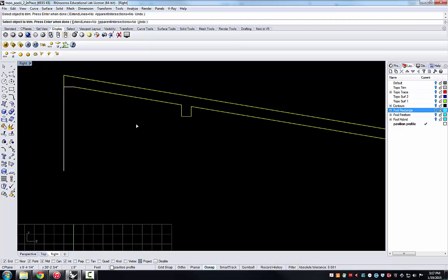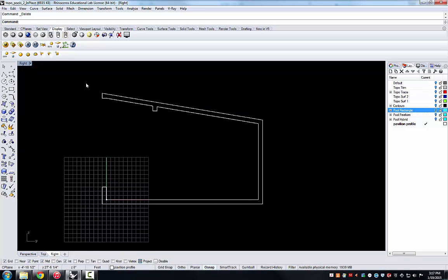To change the exterior profile of this, I'll delete the input line and step back. And what I see here is a good profile for the structure that I want in its basic form and section. Remember, in the future, there will be a line of columns here underneath this beam, and in the next step, we're going to make an interior volume as well. But for now, this we can join, using the join command, into a single polyline that we can use to create the section